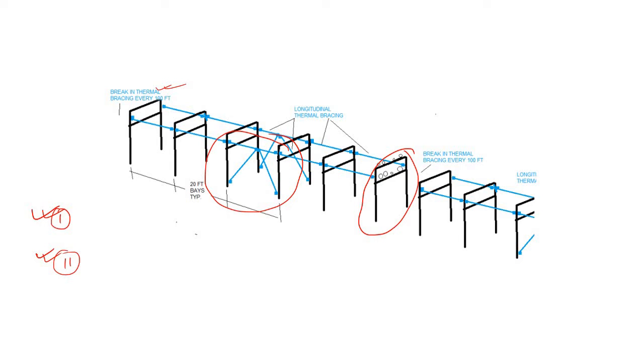Okay, and you know that in many cases, if these pipe racks are going to be built in some Middle East area, in that case you may use some shallow foundation. Otherwise, in American countries you normally provide the pile foundation, and that is a steel pile. Just like this. So what are the forces you need to consider whenever you are supposed to design this steel pile foundation? At the very first I would just like to discuss the portal moment frame.